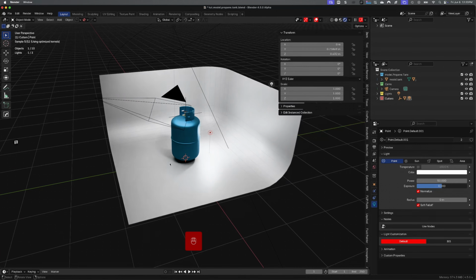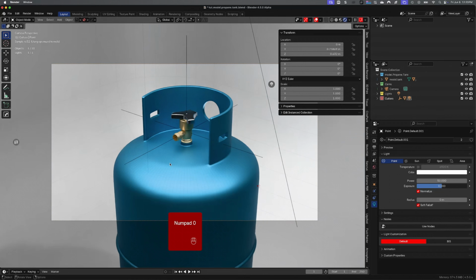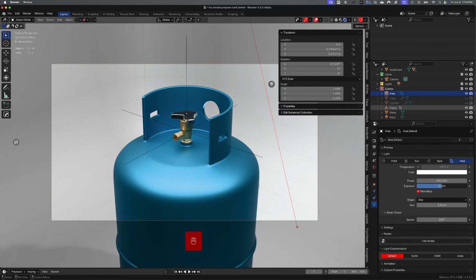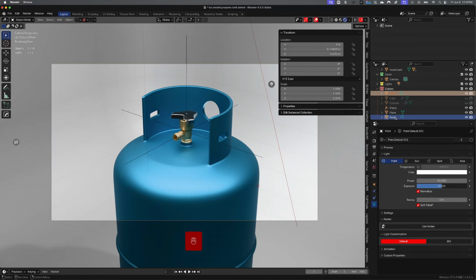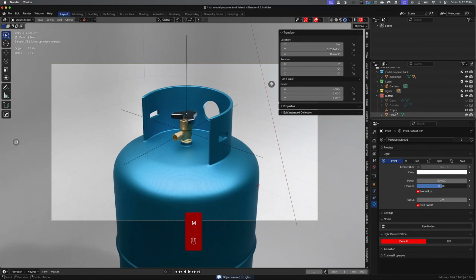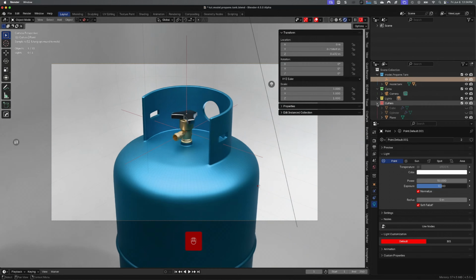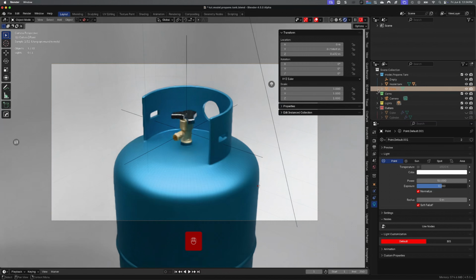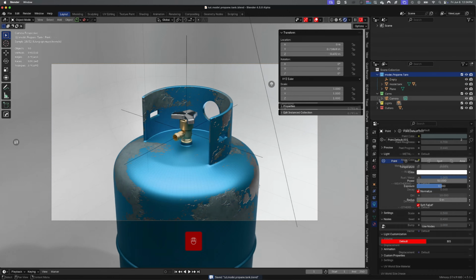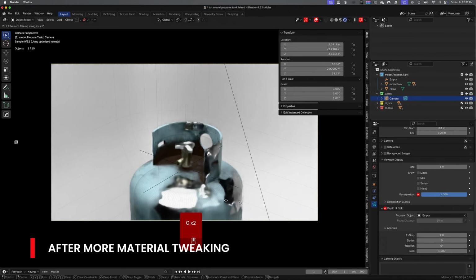Now usually if I'm lighting metallic stuff, I'm putting a light on the left side of it, and then I'm taking a plane, setting the roughness all the way up and using it to diffuse the light back off of it. Or I'll take my area light and a plane, put it in front of that, and put a translucency node in there and make a diffuser in Blender, which actually does really well. However, I think I have an add-on that does this, but I think Blender in the newer versions now supports feathering of lights natively. I could be wrong, don't quote me on that, but I'm almost certain I saw that somewhere.